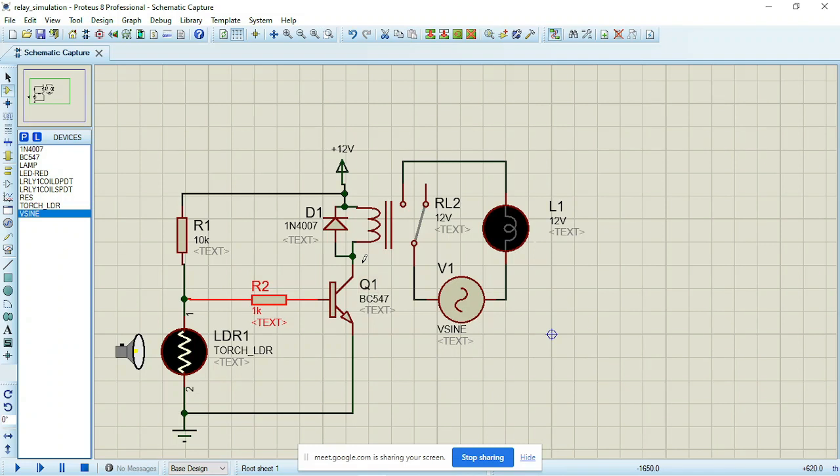As I said before, once you have a coil in a circuit and you turn off the circuit, immediately you turn it off, there will be a backflow of EMF. The reason why we are connecting this diode is that when we turn off, we don't want a spike to go back into our circuit and damage it. So we add this diode so that when that happens, the diode will block the flow so that it will not flow back to our circuit.